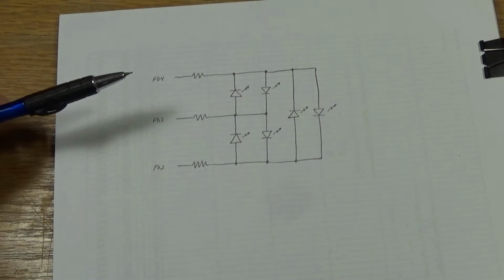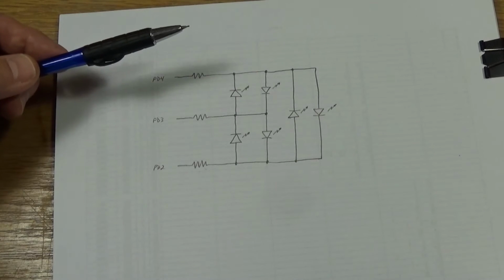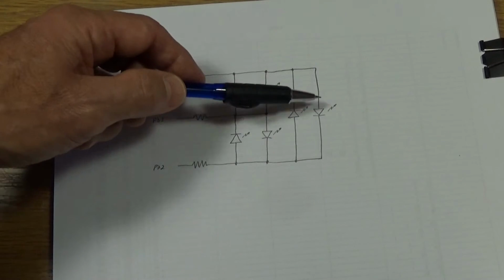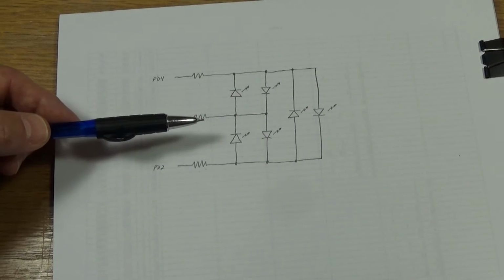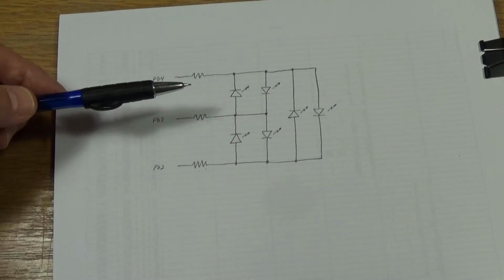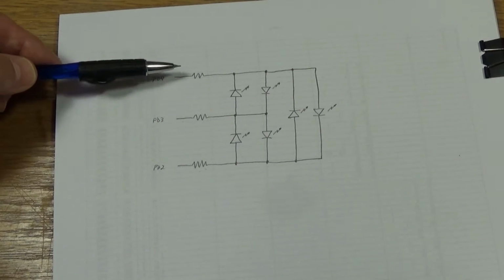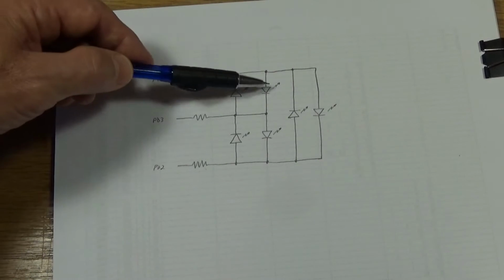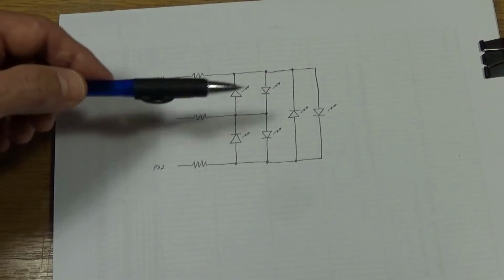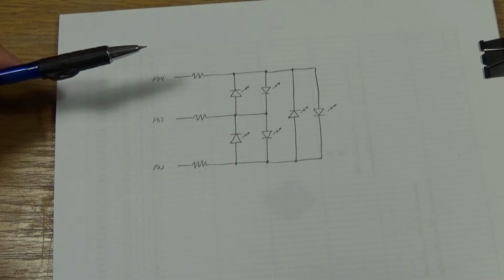And that's the advantage of this, it only takes 3 pins to drive 6 LEDs. The disadvantage of this is that you can only really drive one LED at a time. That's the best way to operate it. If you needed to do 2 at a time, there's only a couple of LEDs that can be driven at the same time. For example, if this is high and these two are low, then this LED and this LED would turn on. And you'd have to really work it out if you wanted to get more than one LED on, but you can't get them all on at the same time.